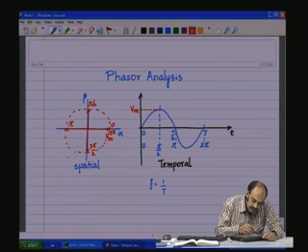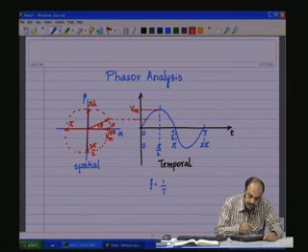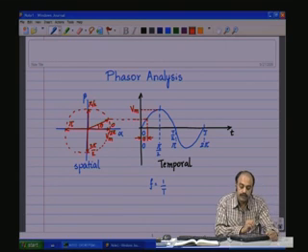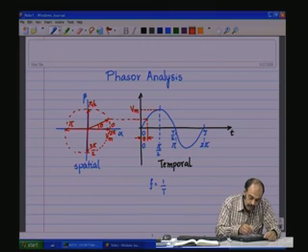And amplitude wise, you should see that vector at this position, at that corresponding angle shift theta, will have a projected amplitude on the vertical axis at exactly the corresponding angle theta from the 0 or the reference. So, likewise, every point on the circle will map onto points on this sinusoid.